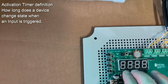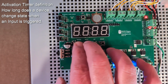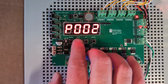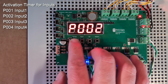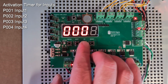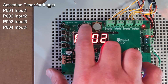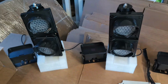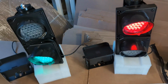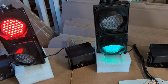So I'm going to go into my programming here. And I'm going to go to P002, which is the activation timer for input number 2. And I'm going to hit enter. And I'm just going to change that to 10 seconds. And then I'm going to hit my exit button or reset button. And what that does is when it comes back, that's for 5 seconds. And this one here will be for 10 seconds.